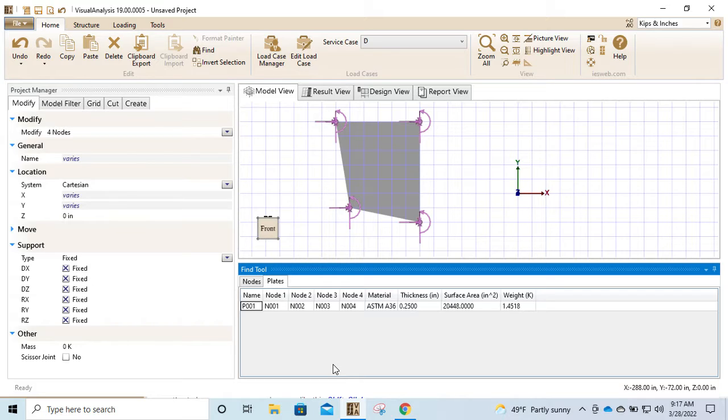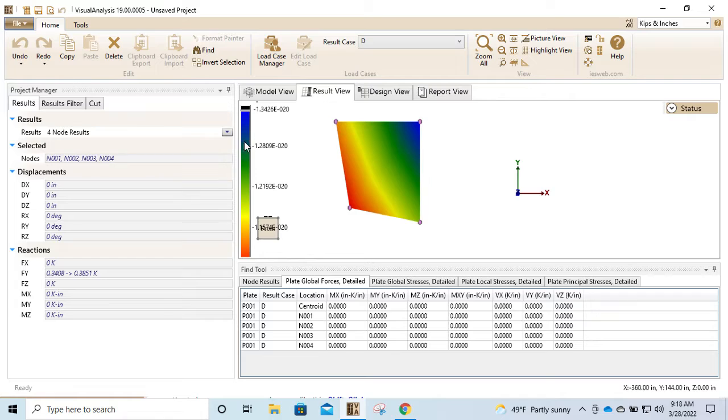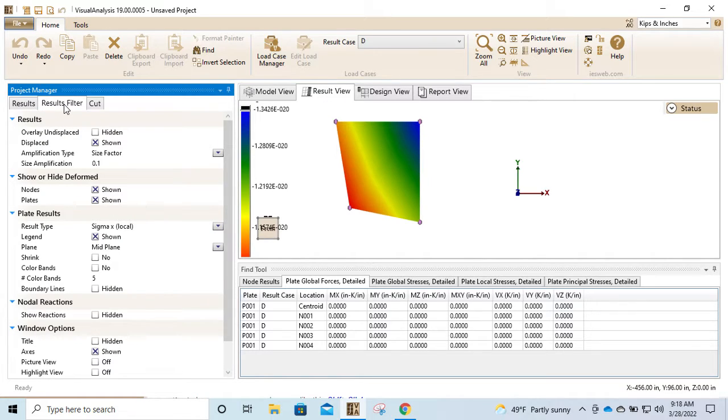And when we get certain results, it'll give you what the magnitude is at the centroid, which is going to be that 5th node. And so you can use those results in some cases to figure out what's going on at the centroid. Also, there's a stress compatibility among those triangles that form that plate. Just like in the result, it seems like there's this even distribution of stress. Maybe that's just the way it is.